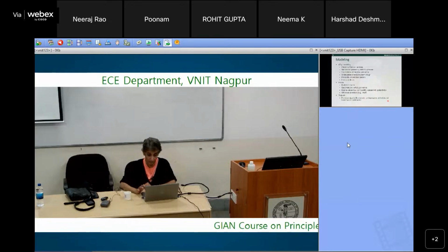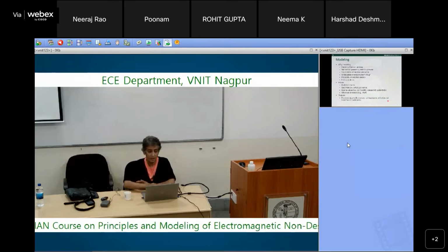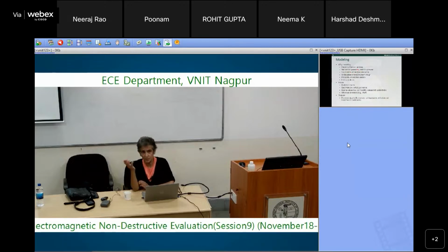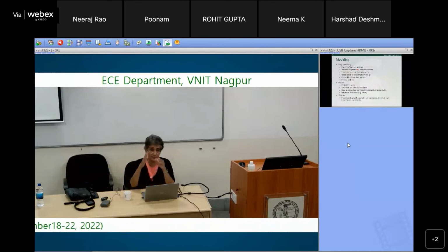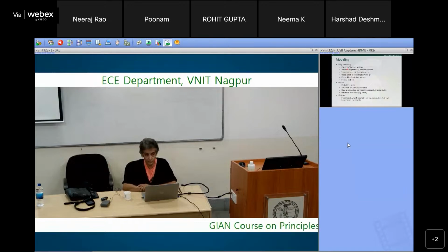Okay. So why do we need modeling? Modeling just gives you the solution to the forward problem. Some of the uses are, it can be used as a test bed for generating defect signatures. Typically, when you want to train a neural network, you want a lot of signal data, and you cannot machine all these defects in different orientations. So the model can be used. With the model, you can do anything and get the defect signature.